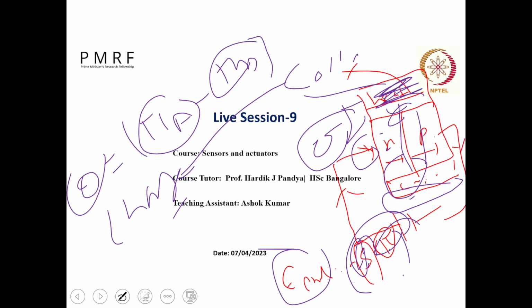Some people write plus minus 5%, some people plus minus 10%. Absolute is like, for example, in the case of the micro heater, we need to have the temperature at around 37 degrees Celsius, right? So 37 is the absolute temperature. Someone said that the absolute error should be 1%, but maybe they said that a relative error should be 5%. So relative error is taking a lot of readings and measuring against the absolute mean value.